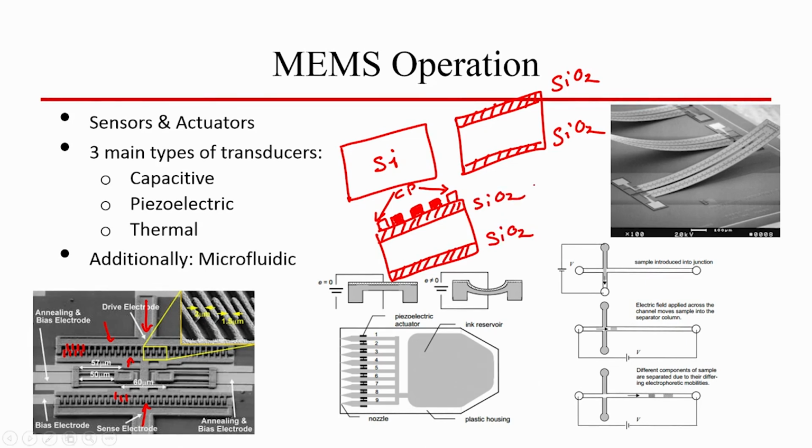Right. Now, what is this? This is the silicon wafer, right. So, silicon is a hard material. If I apply pressure, it will not bend. So, what should I do? I have to create a diaphragm. For creating the diaphragm, we will do a micro machining step.